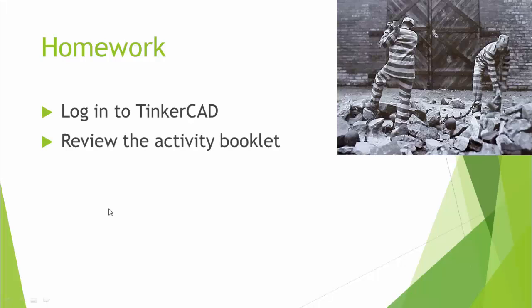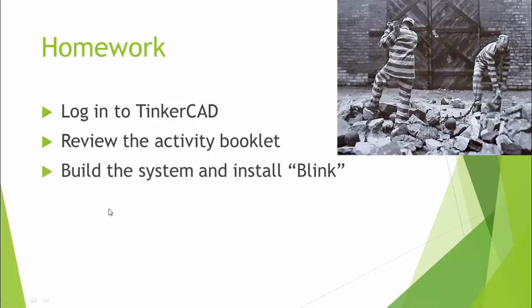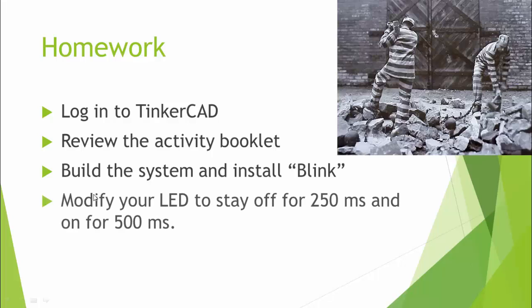So your homework for today, please log into TinkerCAD, review our activity booklet, and then do the simple blink circuit, blinking the LED. Make a quick modification to the code to make your LED turn off for 250 milliseconds and turn on for 500 milliseconds. And that should be enough for today, certainly.